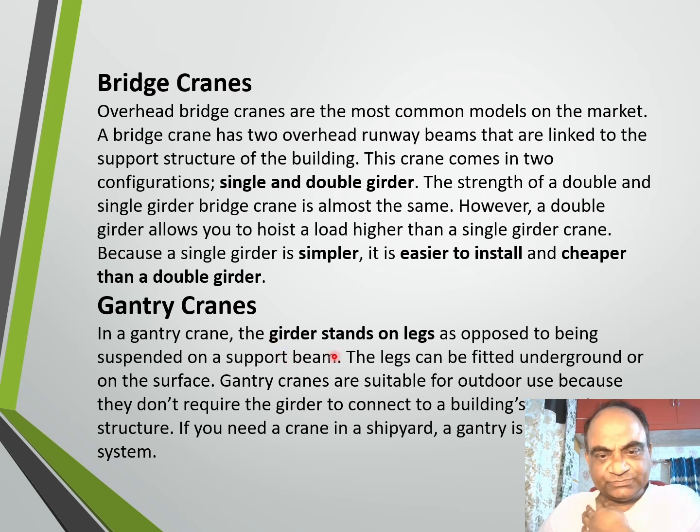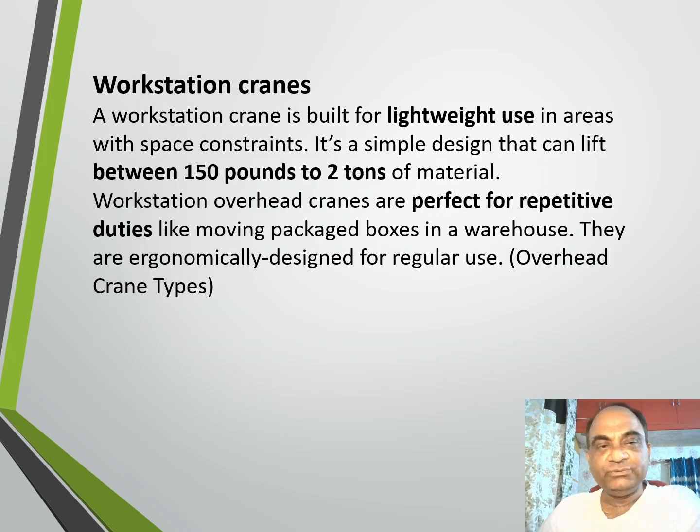Gantry cranes: basically, in gantry cranes, girders stand on the legs as opposed to being suspended on the supporting beam. That's the difference between gantry crane and EOT crane.